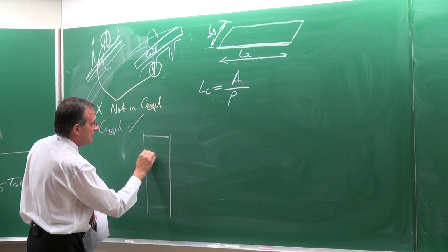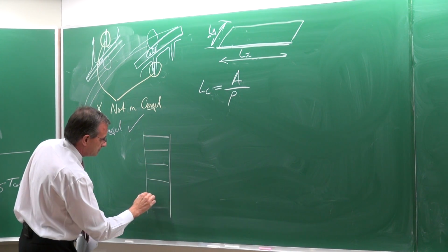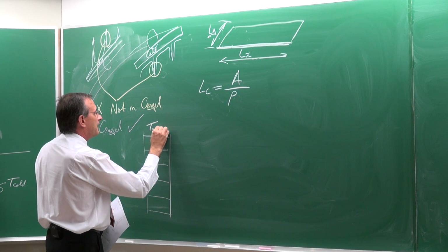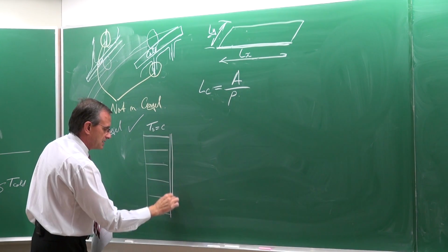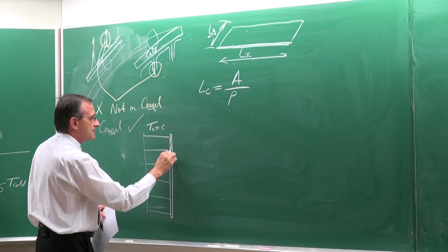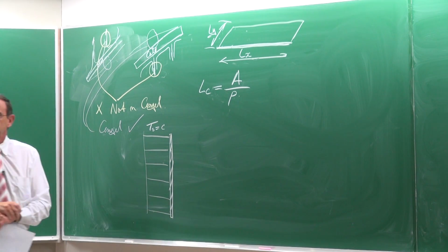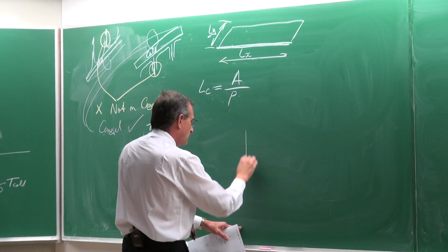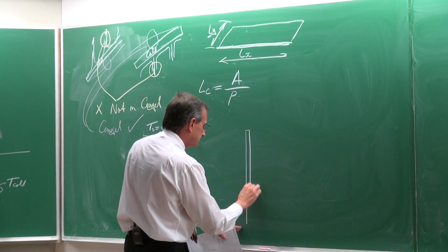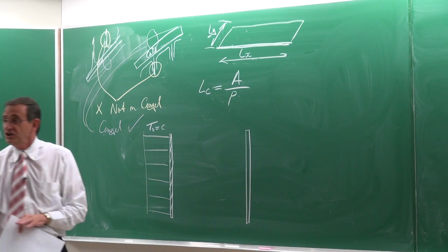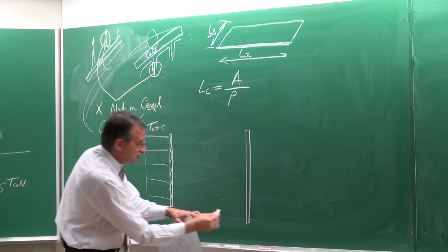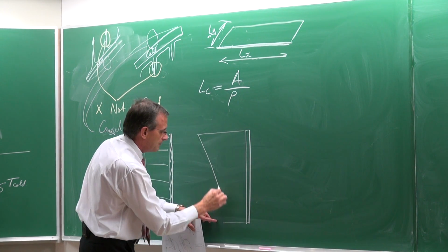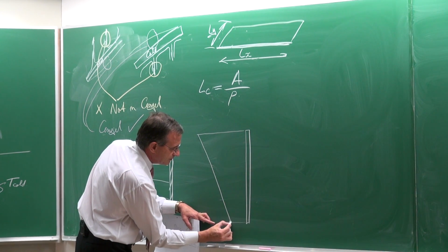So for example, the case with a constant wall temperature. If we look at the temperatures all over the plate, that would be a constant. So there's the plate, like that. In the fine print, it will tell you that the case where you've got a constant heat flux has to be treated differently. For a constant heat flux, your temperature is going to increase linearly, as we've seen previously.